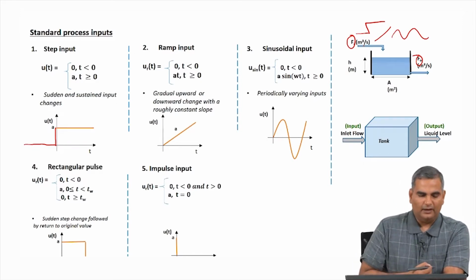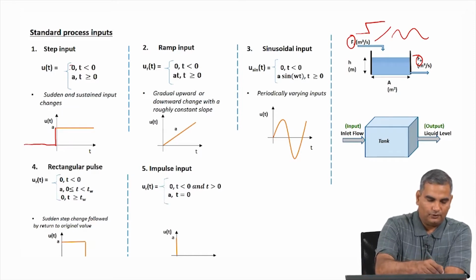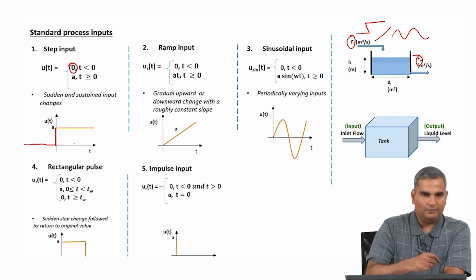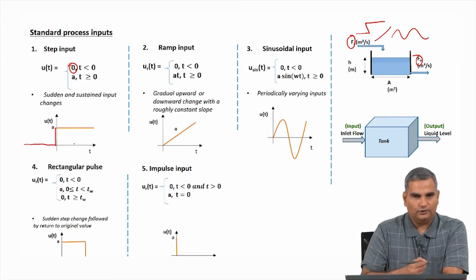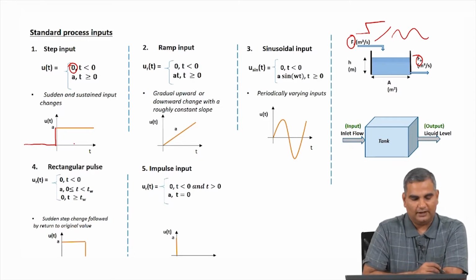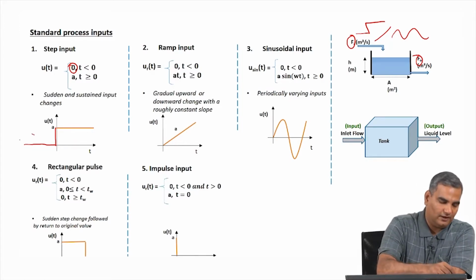Okay. So, you might wonder, I say 5, 7 and so on here, but here I have 0. Basically what we do is, whatever value I am at, I make that 0. For example, if I am at 5 and then I step it up to 7, that is equivalent to saying I am at 0 and I am stepping up by 2, right. So, whatever value of u, I subtract the steady state from that, then the first value is always 0.